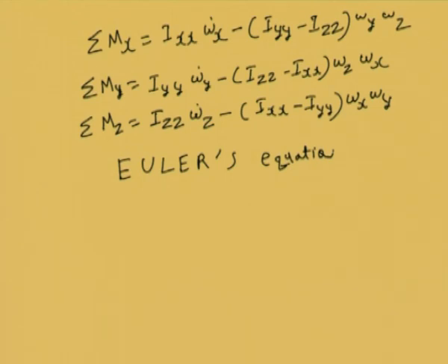However, apart from that, it can also be a point which is accelerating, but the acceleration is either towards the center of mass or away from the center of mass. So there are three types of things. Number 1, the point should be fixed, then you know these Euler's equations are valid. Number 2, the point can be the center of mass.